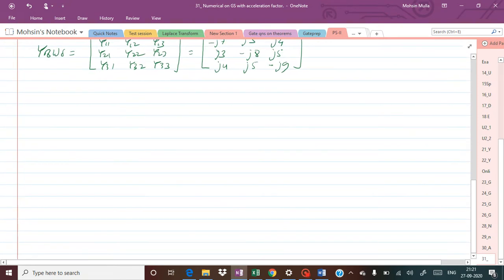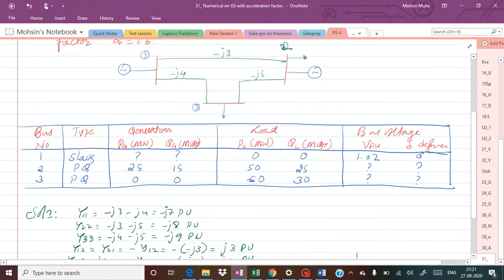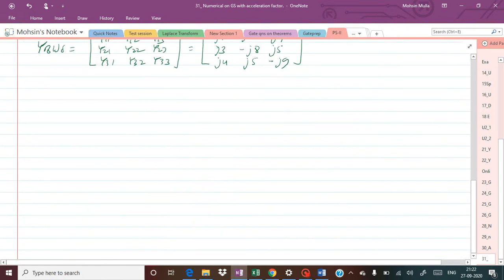Now we shall calculate the bus powers. Here the bus powers are not given directly, but in terms of the megawatt and MVAR rating, but we need to obtain them for the base value. And for a particular bus, if there is a generator as well as a load, the load will be taken as negative and the generator as positive. So we have to find the total power on that particular bus, then obtain the base value of that.